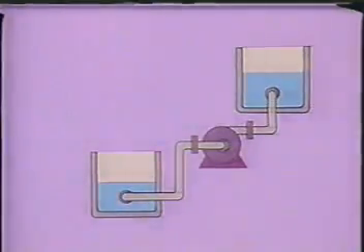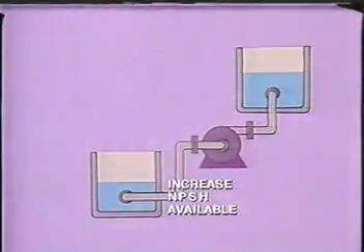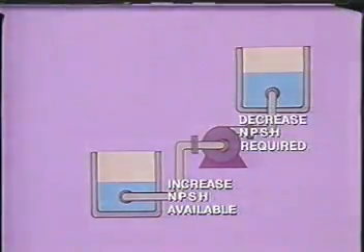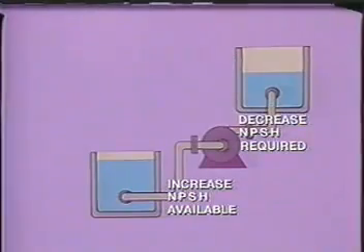Cavitation may be indicated by a crackling noise in the pump and by rapidly fluctuating suction pressure. Cavitation can be corrected by either increasing the net positive suction head available or reducing the net positive suction head required. Net positive suction head available may be increased by increasing the liquid level or pressure on the suction side